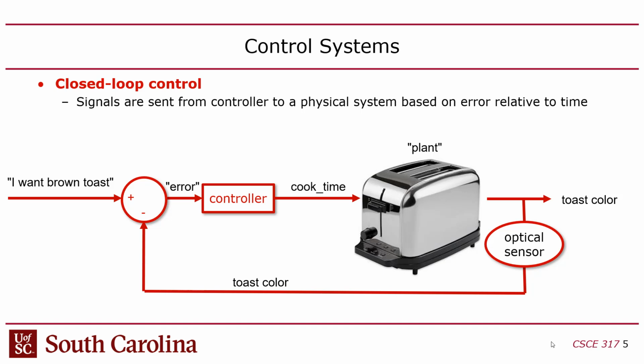And then you can have closed loop controllers where you have some kind of a sensor in the plant, and then usually that comes back and you calculate an error value. So the sensors are used in combination with the set point. In this case, I'm doing a difference operation between them, but it can be more complex than this. You take the set point and the sensor readings from the plant, and the combination of those serves as the input to the controller, and then the controller sends a signal to the plant. This feedback signal is usually called a process variable, and this is called a manipulated variable. The manipulated variable is what the controller sets.